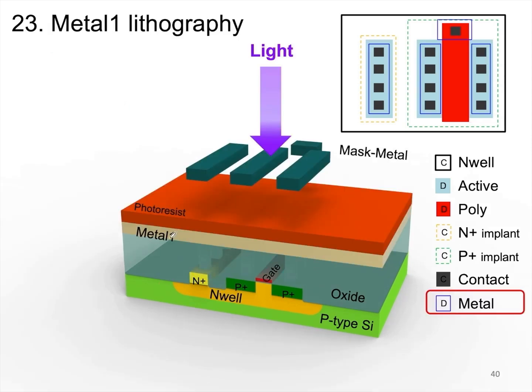First, we need to connect M1 to our metal, so M1 will be linked to our metal, right? Then we need to preserve our interconnect lines. After that, we will spin coat photoresist on M1 and etch it. The etching process means we need to keep the patterns we want, which are the necessary metal interconnect lines, while removing the unnecessary ones. So during the photolithography process, we need to retain some of the interconnect line patterns.